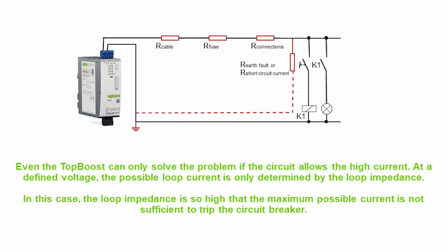For that, we have an electronic circuit breaker which can trigger by a specific characteristic on the overcurrent. So maybe you have just an overcurrent of twice the nominal current. The electronic circuit breaker will trigger as fast as possible. If we have such a case with a long distance between short circuit and the circuit breaker, the electronic circuit breaker is a better solution.